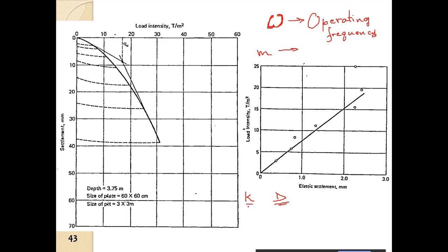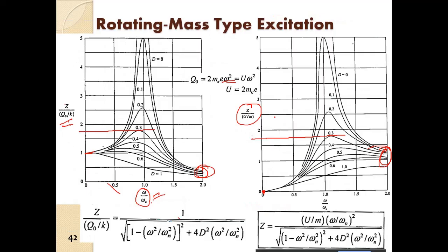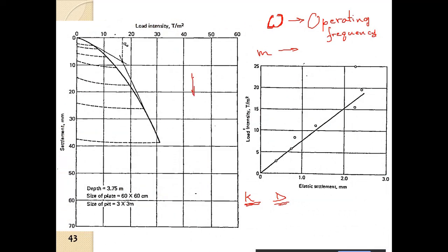But we now have to obtain the spring constant for the various motions. If you recall, we have the translational motion about Z, the rotational motion about Z, the translational motion about X or Y axis, and the rocking and pitching motion about Y or X axis. So what are the things that we need to determine? We need to determine Cu, which is the coefficient of elastic uniform compression.